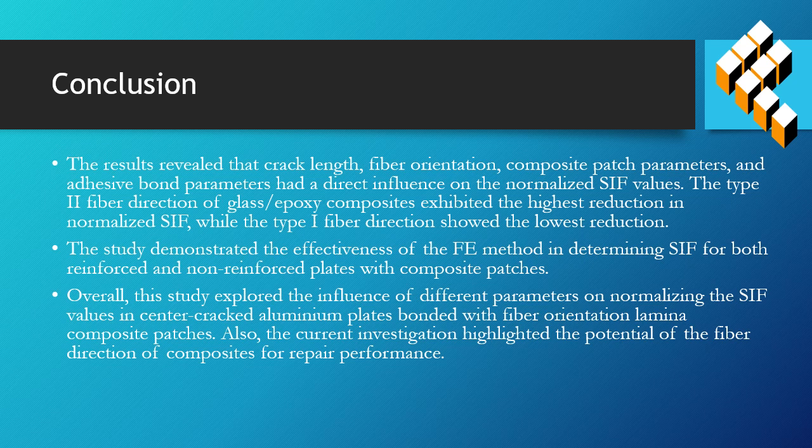And we have found this study is significantly important for reducing the crack length, or you can say crack control, in thin wall structures. To demonstrate this study, we have only considered the finite element method, and this can be extended using experimental work and other methodologies. This study explored the influence of different parameters on the normalized SIF values in central crack aluminum plates bonded with fiber orientation lamina composite patches.